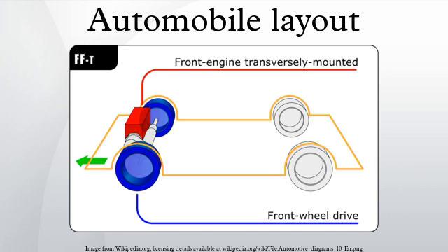This issue is particularly noticeable on pickup trucks, as the weight of the engine and cab will significantly shift the weight from the rear to the front wheels. Rear-wheel drive cars with rear-engine or mid-engine configuration do not suffer from this, although fishtailing remains an issue. To correct this situation, owners of RWD vehicles can load sandbags in the back of the vehicle in order to increase the weight over the rear axle, however speeds should be restricted to correctly predicted available grip of the road.